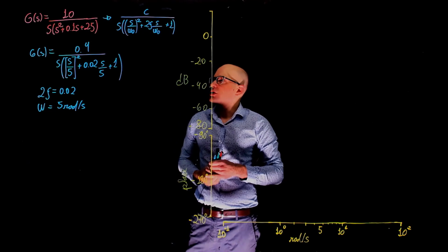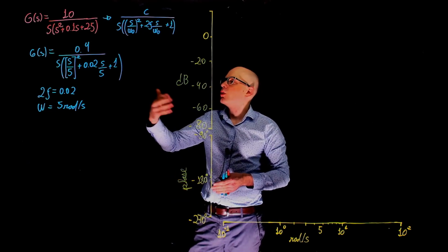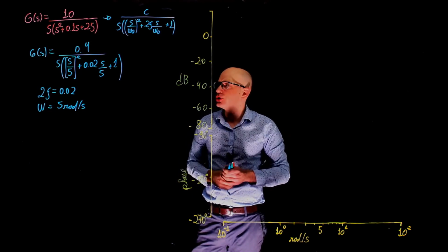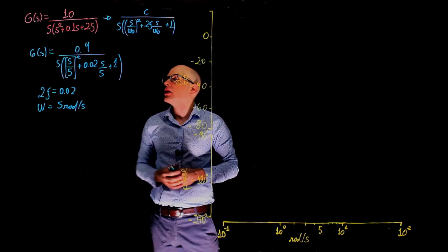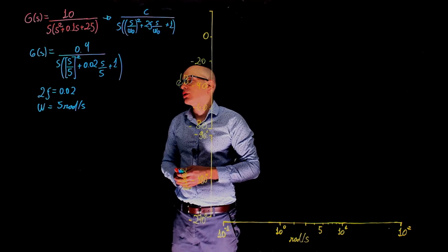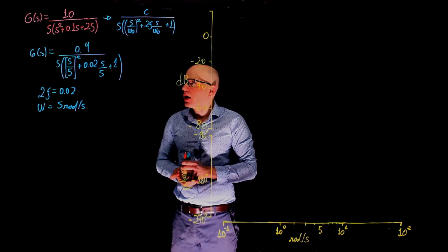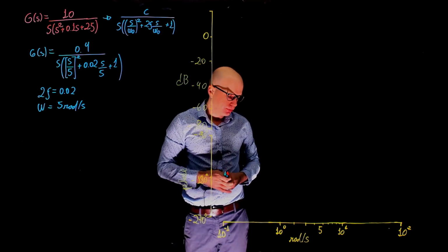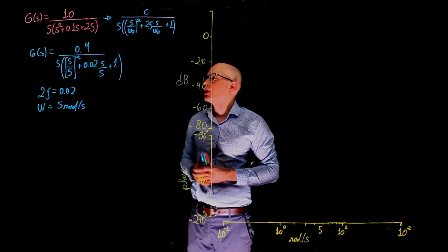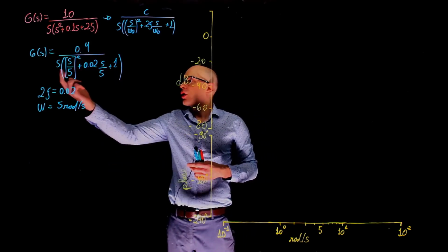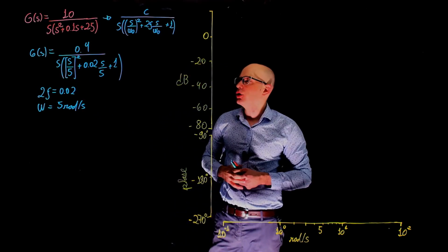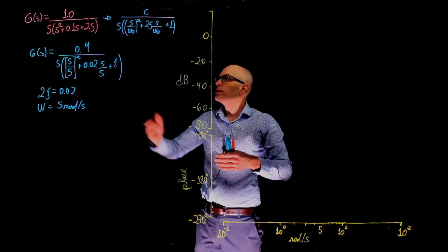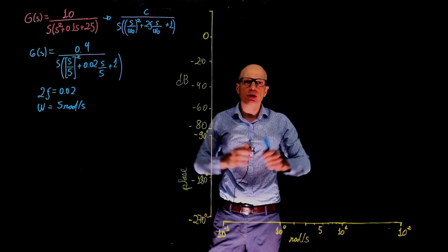In the previous examples, we started by looking at very low frequencies and determined what was affecting the Bode plot at low frequencies. That was relatively easy because it didn't have zeros or pole at the origin, which is not the case here. Here we have a gain and a pole at the origin, and that will affect the Bode plot at low frequencies. So how do we account for that? Now we need to account for the slope added at all frequencies by this 1 over s, by this pole at the origin. In addition to the pole at the origin, we have the gain. So we have these two things to account for: a constant slope coming from this pole, which is negative 20 decibels per decade, as we know, passing at 0 decibels at 1 radian per second, 20 log of 1 is 0, and the gain at 0.4, which will make the Bode plot shift up or down.